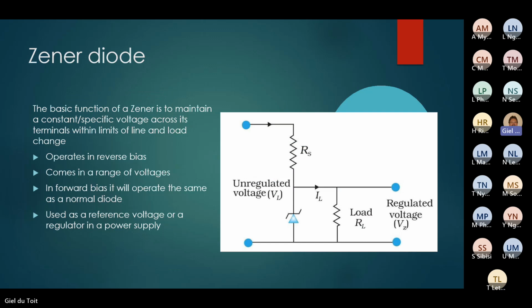So a zener diode basically can work only in reverse biasing. Now look in this funny case. The diode is upside down. So the positive of the battery goes through a resistor to limit the current. Remember I said we must limit the current. Now, to limit the current to say half an ampere, we must put a resistor here big enough.